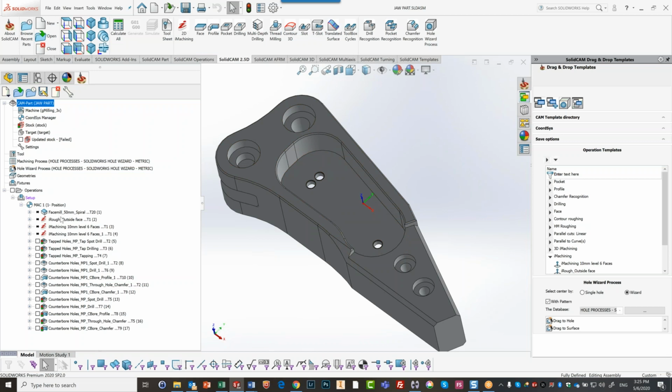Okay, so it'll give me a change over here, but it won't change the tool for me in that particular case. And therefore, I may have to go back into the operation and change the tool I may need. But you'll see that as it happens, because you'll see a toolpath that doesn't cover everything, or you may even have an empty toolpath because the tool cannot even go in there.